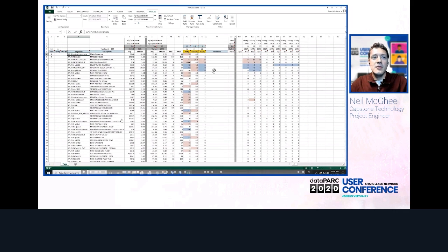One of these statistics that we've already looked at is likely to bring to the top the tags that we are looking for. However, it also may bring to the top other changes that are trivial or unimportant. If we have pulled these tags from other displays that we already know have important tags, then this can help remedy the issue. However, if we have imported all of the tags from an entire process area, we might have imported many tags that are less important to the overall process. To combat this, we can use some of the built-in tag sorting features.